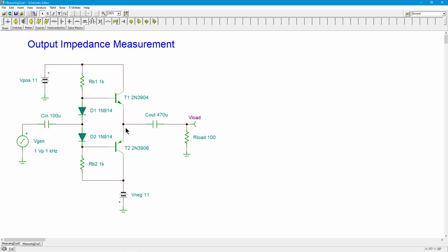That's not really a good idea with a power amplifier, because the power amplifier impedances are usually a lot smaller than what your load is. And you can get some really nasty distortion, clipping, overheating, maybe transistors go bye-bye on you. So this way, the way I'm doing it here, it's a little tiny bit more calculation, but it's safe.